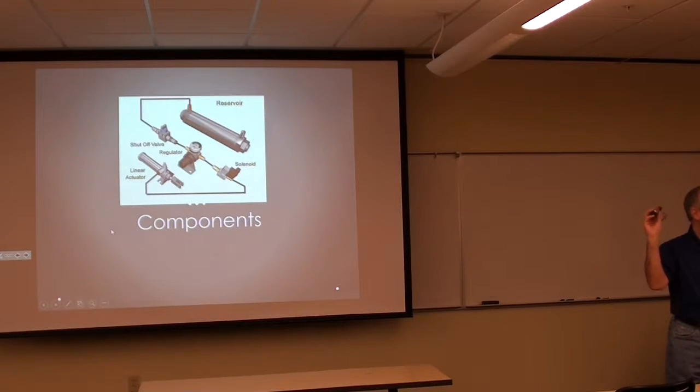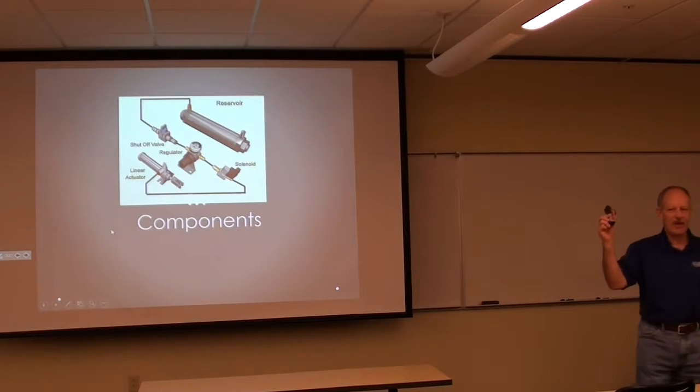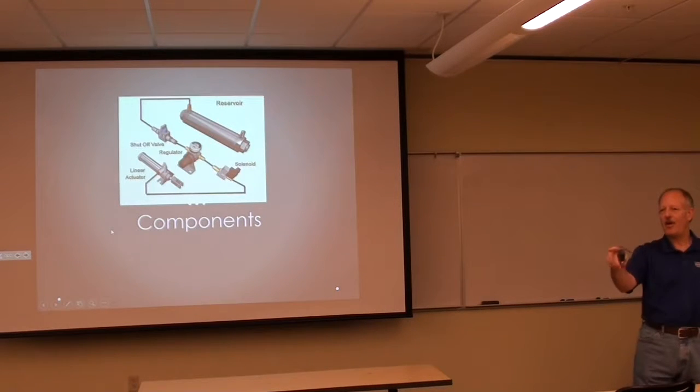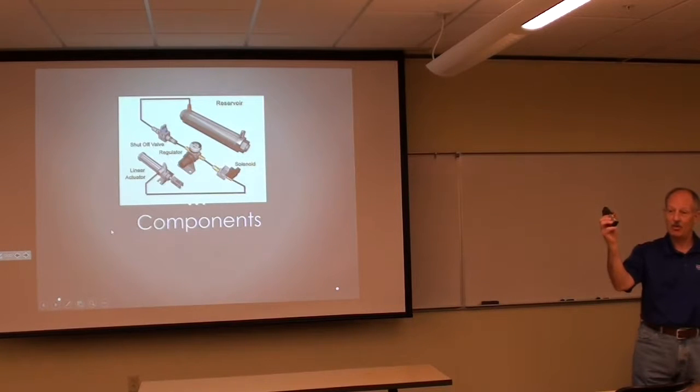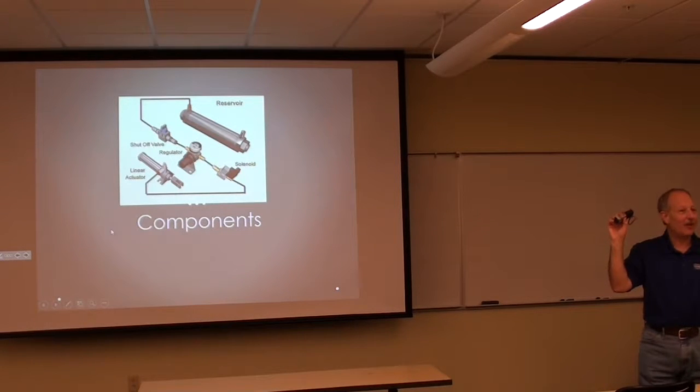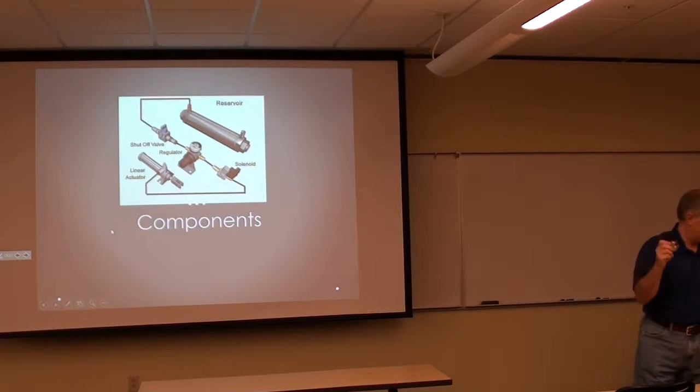Yeah. So what happens on your robot when, at the end of the match, you get the disable from the FMS? What happens on your roboRIO? All solenoids return back to that. Well, yeah, more generic than that. What happens when all outputs are disabled? So what that means is this solenoid valve is going to de-energize. That means you could get movement after the match is over, right? Now, I'm not suggesting you do that, because it could be a good thing or it could be a bad thing, right?